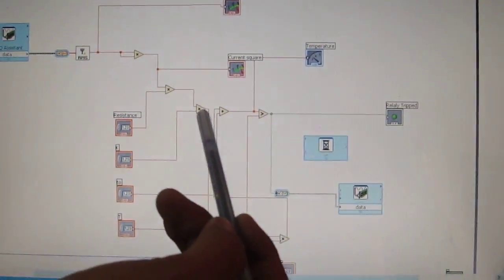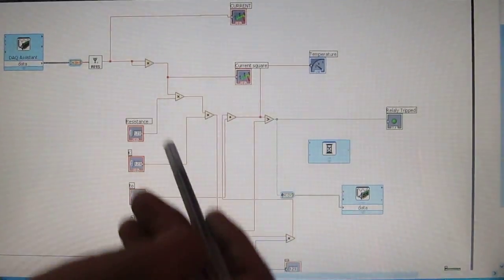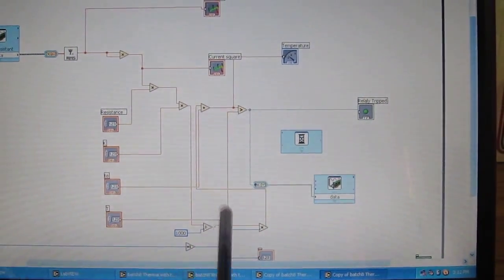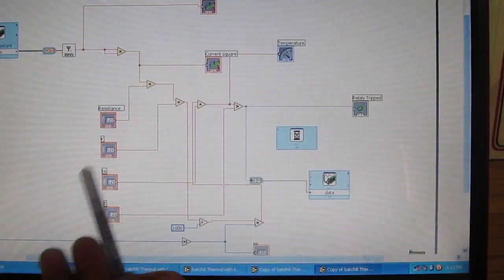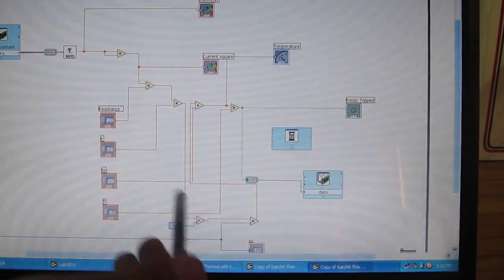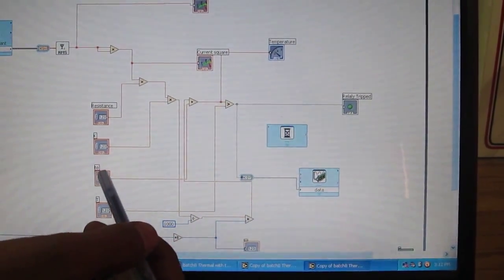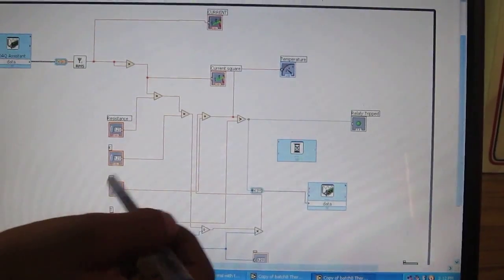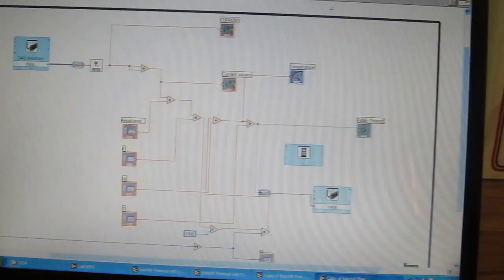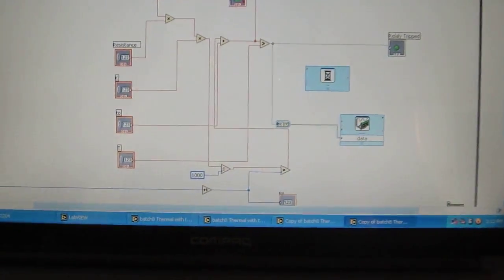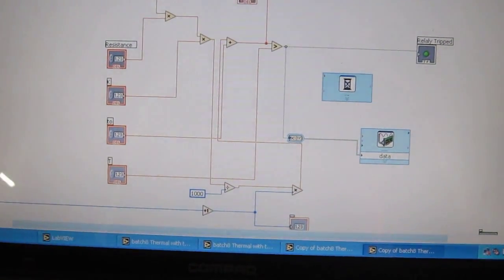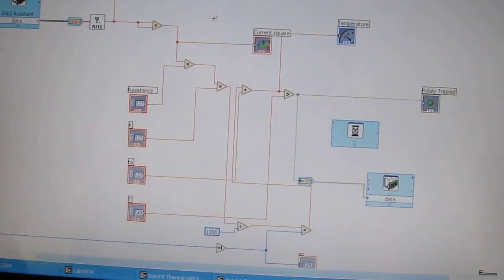Here all the signals represent the temperature signal in terms of voltage. So here I am going to add the initial room temperature T0. T0 is nothing but our actual normal room temperature, like 26 degrees centigrade or 27 degrees centigrade. I am going to add this initial room temperature to the actual winding temperature. Here the capital T is the safe value of working temperature for the motor. The motor safe working temperature is given with ambient temperature as 40 degrees centigrade, so I kept the safe limit as 40 degrees centigrade.